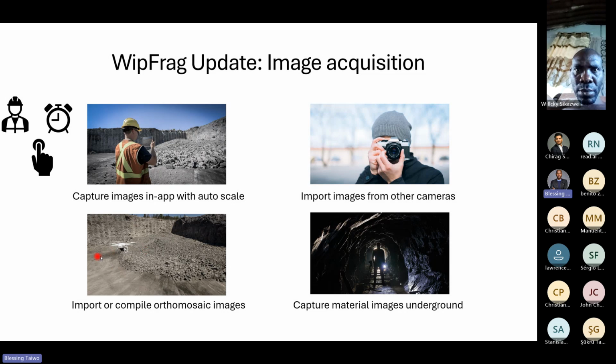Then you can also take the picture of the blast with a drone. There are two advantages of taking the blast image with a drone. The first thing is that you will have access to the blast cap, the upper side of the blast, that is, blast material that is coming from the stemming zone.